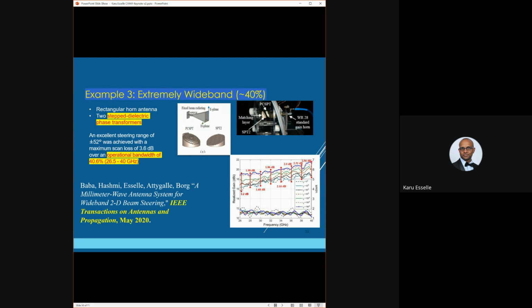Because in a typical unit cell design, you have the scattering parameters, right? The input reflection and the transmission. Yes. And you need to optimize the cells so that the reflection is very small. If you design it that way, then you don't have to worry, even if they are in the near field. Okay, sir.